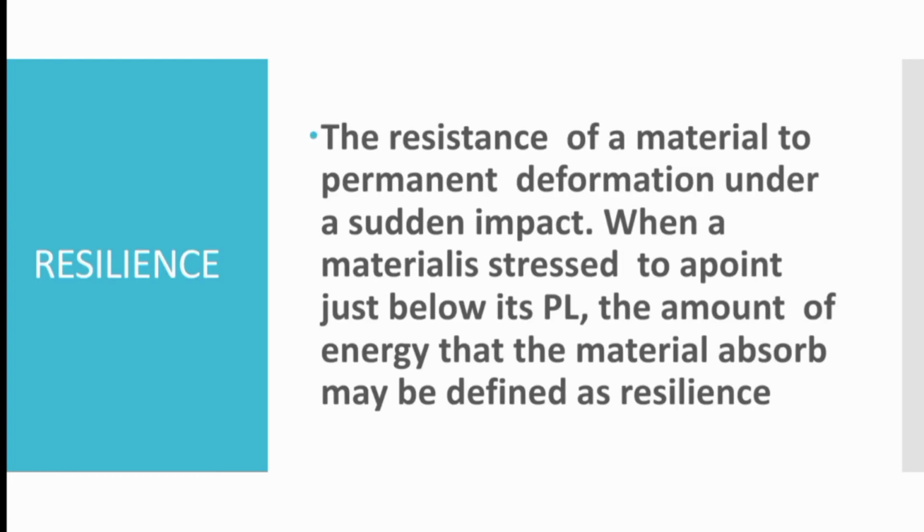Now, let us study what is resilience. Moving to the definition of resilience: the resistance of a material to permanent deformation under a sudden impact. When a material is stressed to a point just below its proportional limit, the amount of energy that the material absorbs may be defined as resilience.